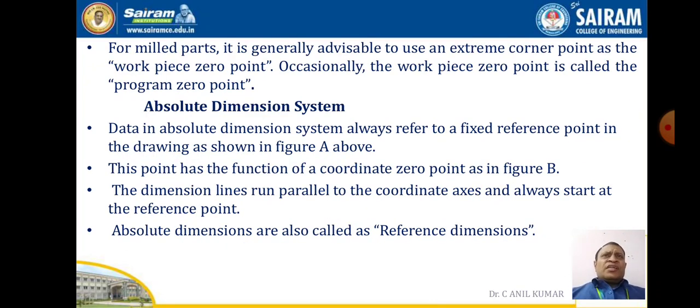Now here in this case, these are the three different types of points. Normally any machine tool will have either a machine 0 point, or a reference point, or a workpiece 0 point. Normally while doing the program, we are going with respect to the workpiece 0 point only.